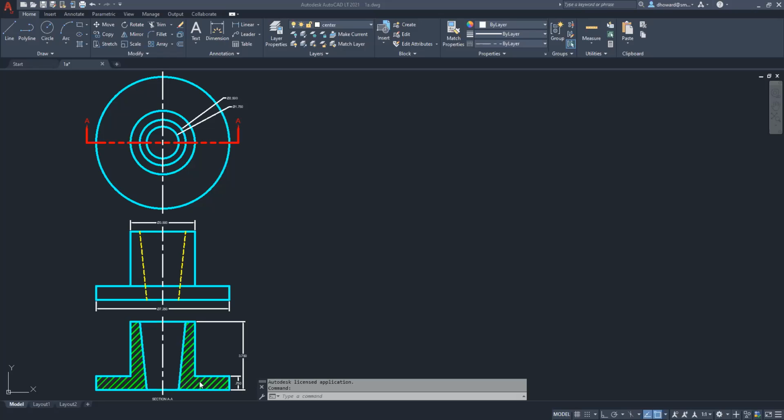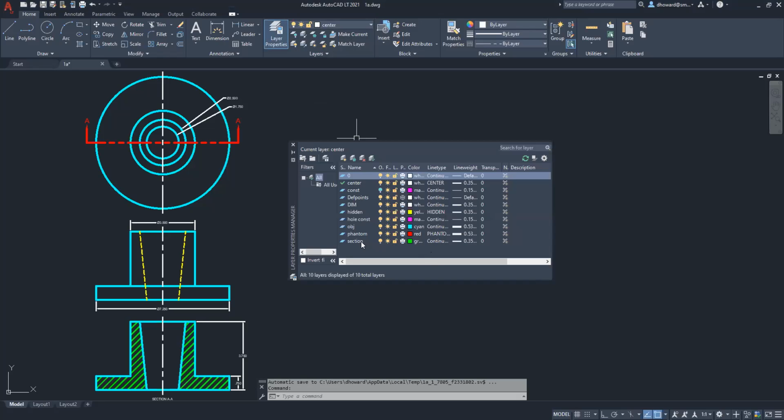Okay. So probably before we do any drawing, we ought to take care of that. Let's go to layers and check that out. So you can see that I have a new layer here. I will click on it, called Phantom. And you could make that simply by creating a new layer. I'll do it with you right now, naming it Phantom.